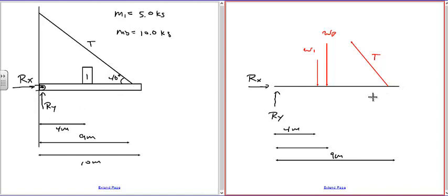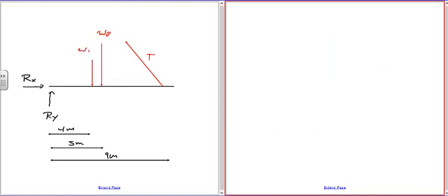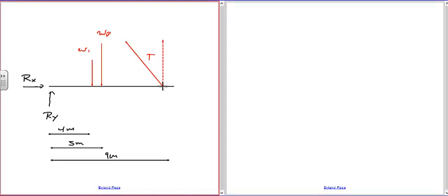We have an extra meter here that's to the right of the support wire. And then the middle is 5 meters because the total length of the beam is 10 meters. So the distance to the middle of the beam is 5 meters. So again, we're taking the weight of the beam and concentrating that in the middle of the beam. So that's our free body diagram. Now, just like we did in our previous experience, we took anything that was at an angle and we broke it into two components.